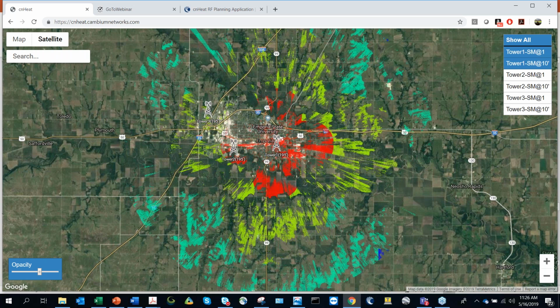You know your environment best and what packages you can offer for different RSSI levels, because you have different interference at different locations. So we allow you to specify the RSSI levels you would like for each color. For example, maybe you start off with negative 55 as your first color, red, so everything at negative 55 and up would be red.